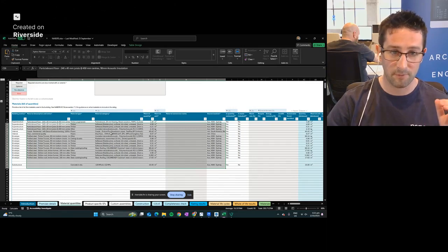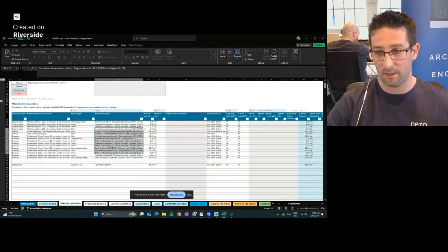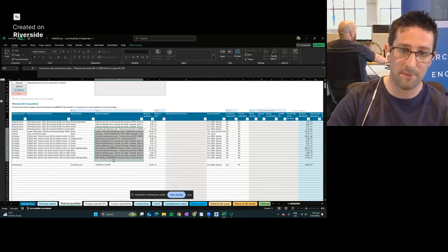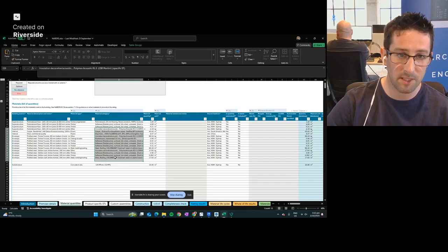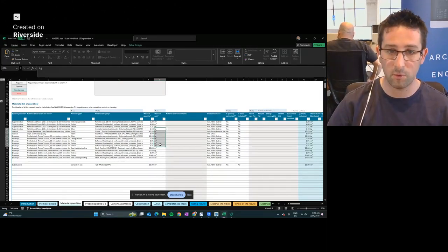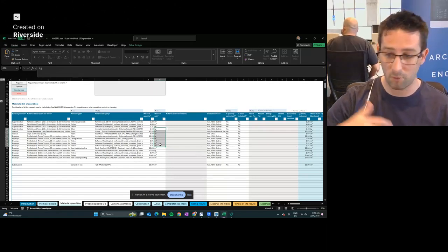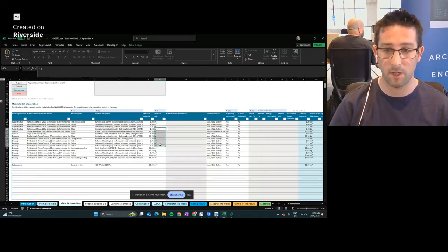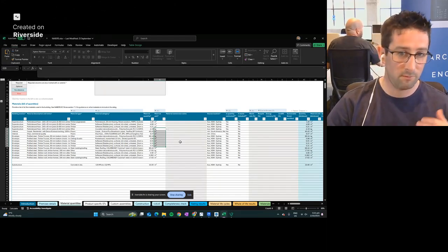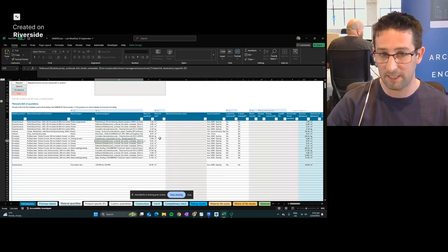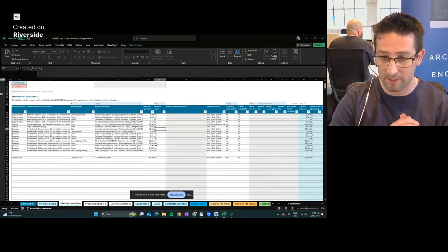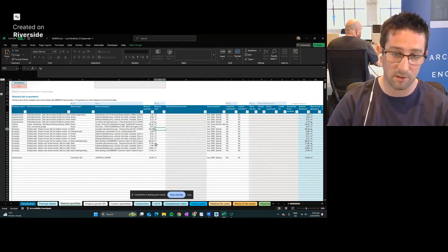We have identified the material volumes, the carbon emissions data, and converted that back to what building science requires. So you can see a lot of material in here is not in the bales of insulation and the boards of plywood that the quantity surveyor might price, or the square meters of wall cladding, or the cubic meters of concrete that the designer might think about. Things are brought back into cubic meters of chipboard, kgs of steel in your cladding systems, things like that. So all that conversion is done behind the scenes. It happens within the 10 seconds it takes to download that Excel document to your desktop.